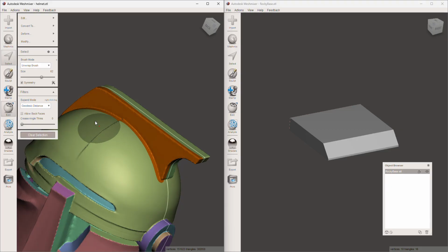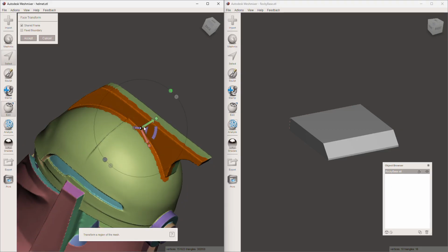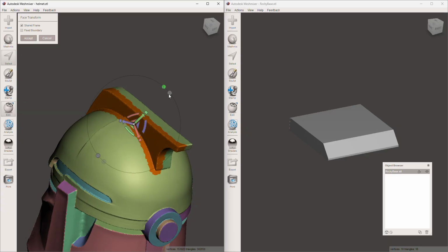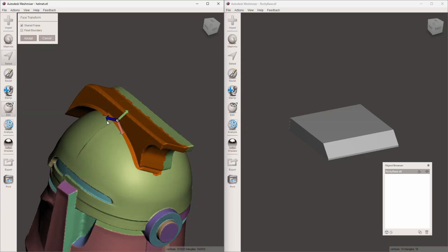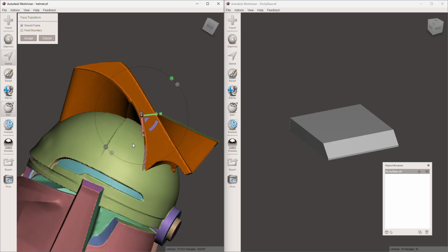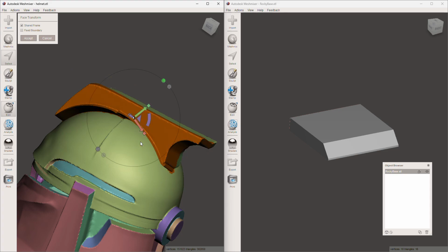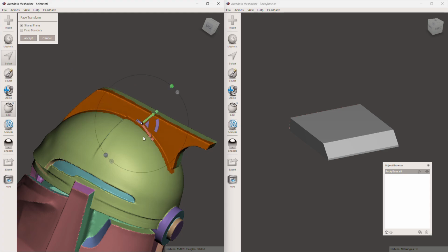And the next trick is using the letter T, which is transpose, okay? So now we can transpose that specific panel. We'll hit T, and we can pull it out here. We can rotate it. We can do all kinds of different things, okay? Anytime you see this surface show up, that's no good because that means the underside is showing, and it won't print right. So do Control Z there, okay?